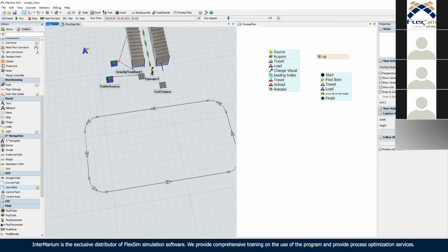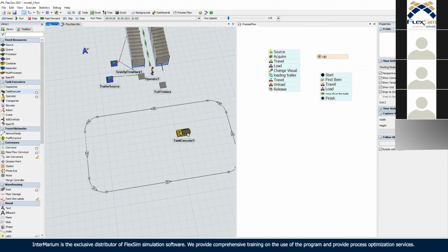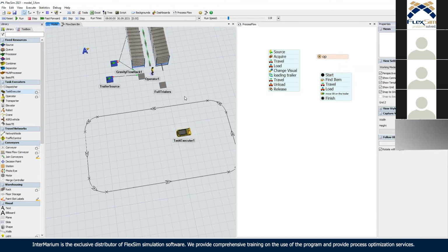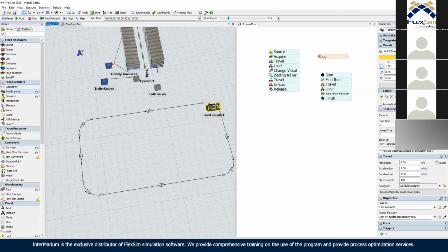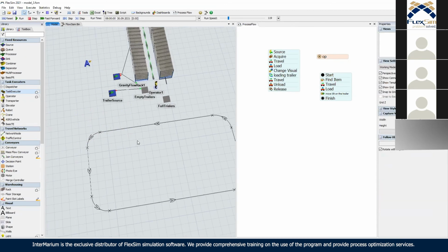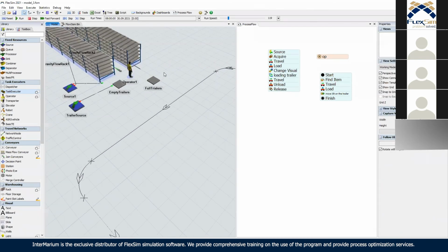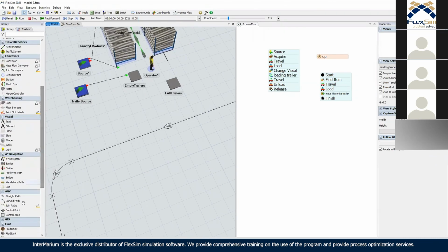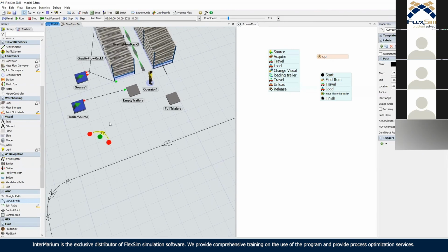Well, this is my base path. Because we'll have some AGV, I want my AGV to pick up this trailer in a very specified way. I want him to go like this, then reverse here, attach the trailers, and then continue with the loop. So I need to prepare the road to approach these trailers. This we will do by hand using some curved paths.